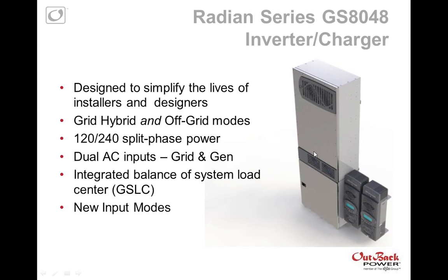We've integrated the balance of systems into a load center you see here at the bottom. The top part is the inverter. There's just a back plate that mounts on with 4 lag screws. There's a little bracket on the back that just mounts over that. So it goes on very quickly. You can get the pre-wired versions that have the circuit breakers and our integrated bypass already pre-wired in there. You just land your field wires onto some screw terminals, and that's pretty much it.